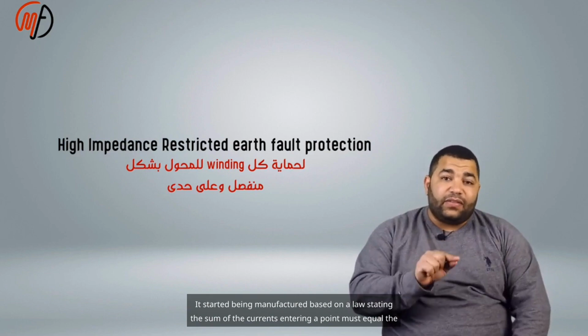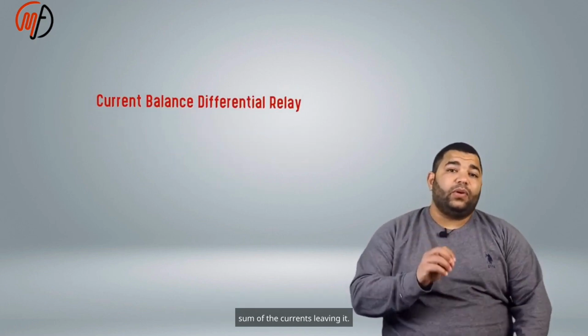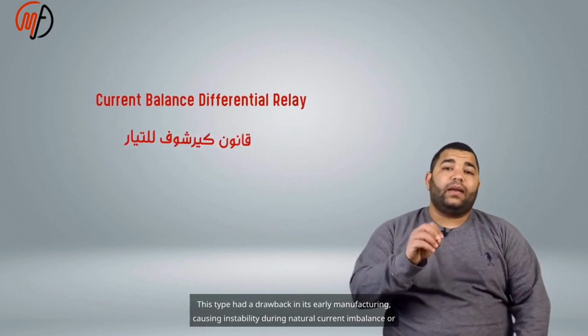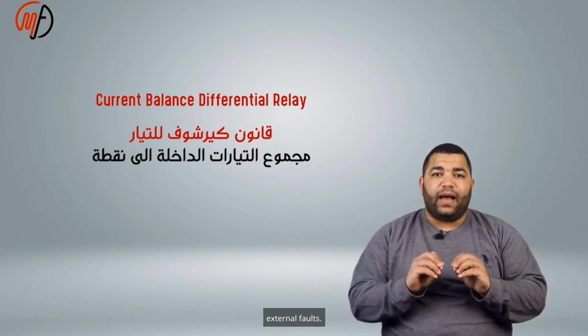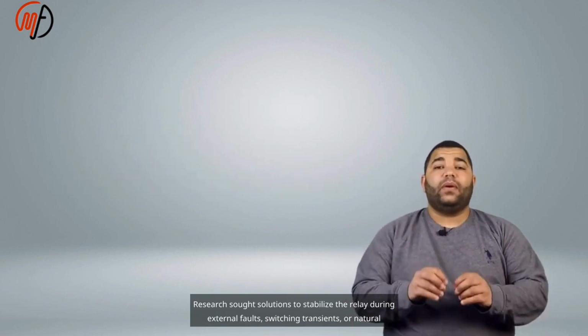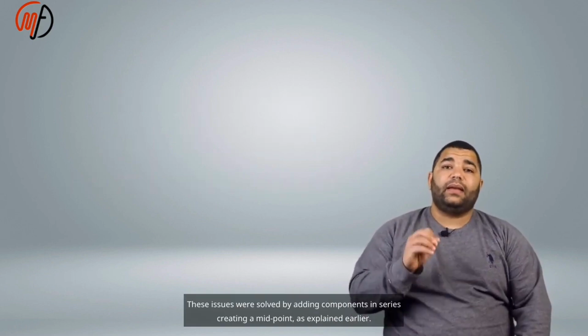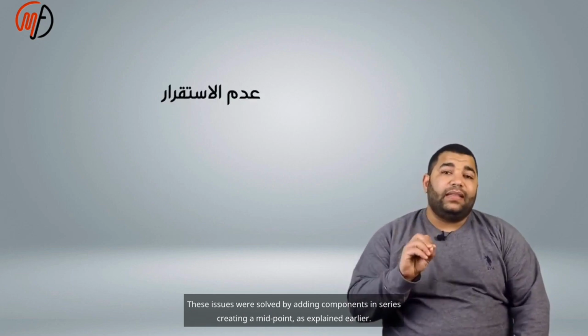It started being manufactured based on a law stating the sum of the currents entering a point must equal the sum of the currents leaving it. This type had a drawback in its early manufacturing, causing instability during natural current imbalance or external faults. Research sought solutions to stabilize the relay during external faults, switching transients or natural currents.